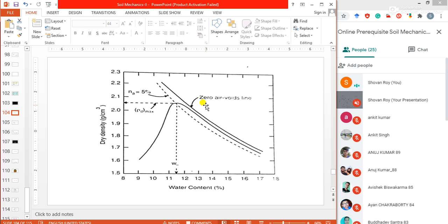The double layer depression leads to a low interparticle repulsion, and the particles do not move over one another easily when compacting energy is applied, and hence a high percentage of air voids and low density is achieved.